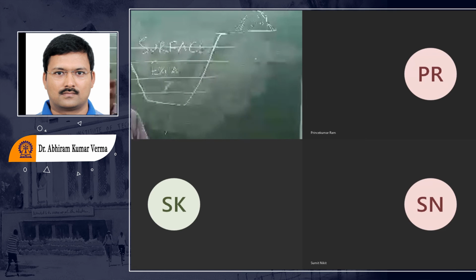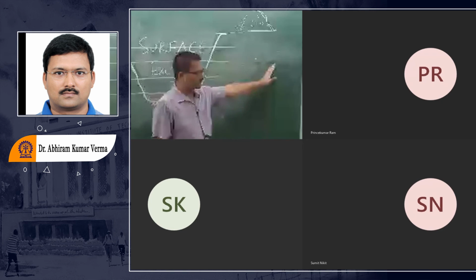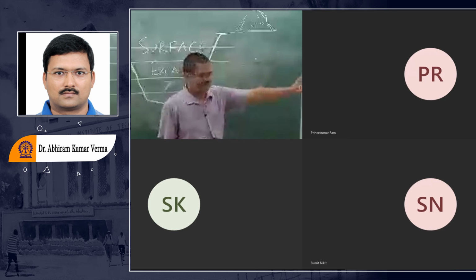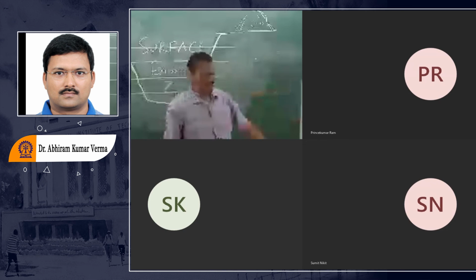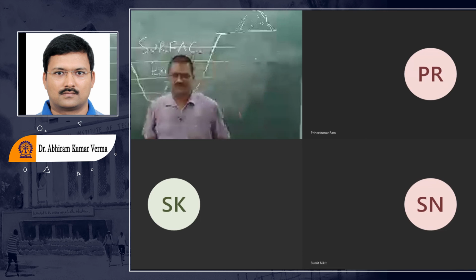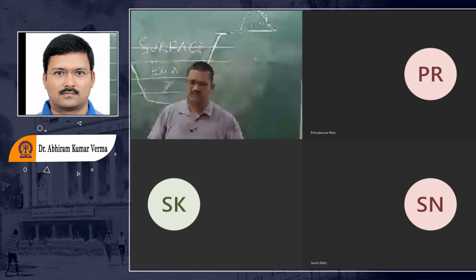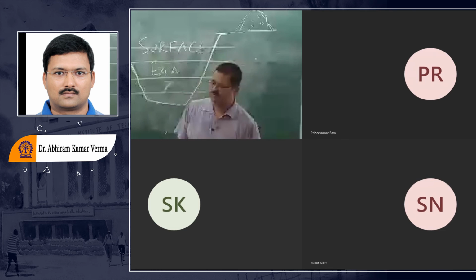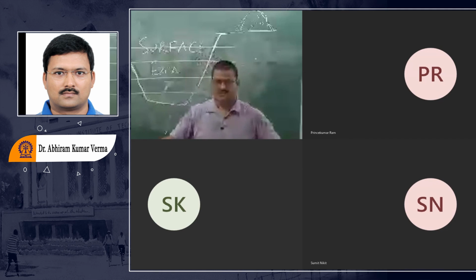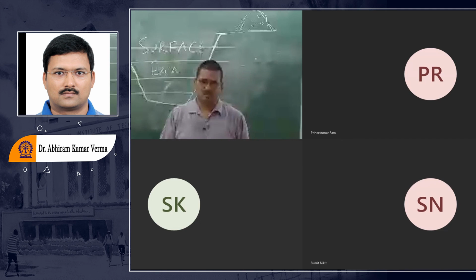And you will find that as we go away from these excavations, maybe four times, five times the size of these excavations, the stress field shows no change. Now the stress field becomes equal to your in situ value. So the area around these excavations gets affected by such excavation activities, and as the size of your excavations becomes more, the size of your zone of influence will be more.